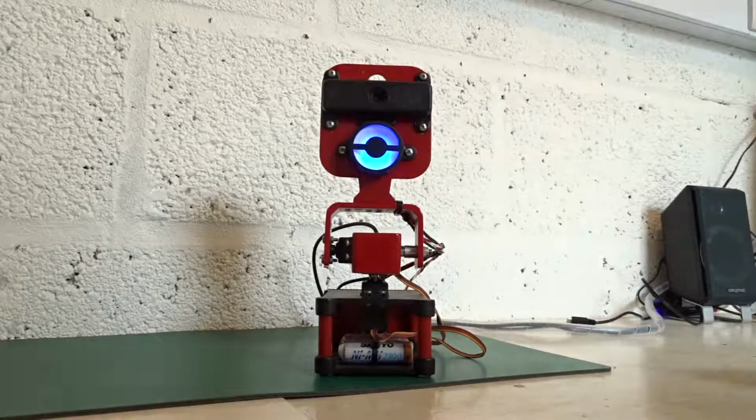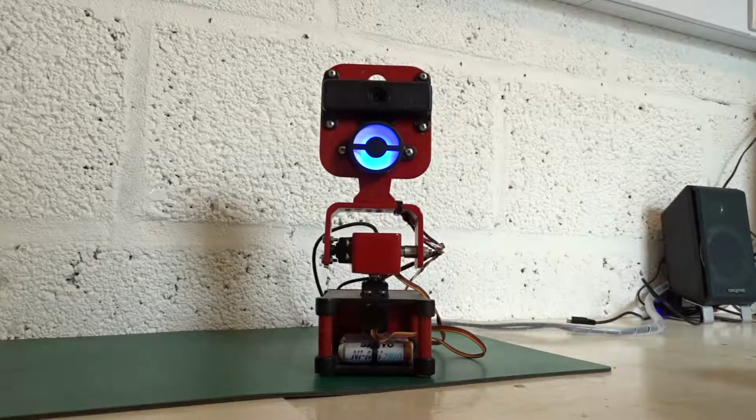So once that was working, I wanted to do something a bit more interesting and actually convert the two neural patterns from the yaw and pitch values into a two-dimensional neural sheet, if you like, where the pattern on there is almost like a hill of activity, the peak of which represents the yaw and pitch position of the robot head at the time.